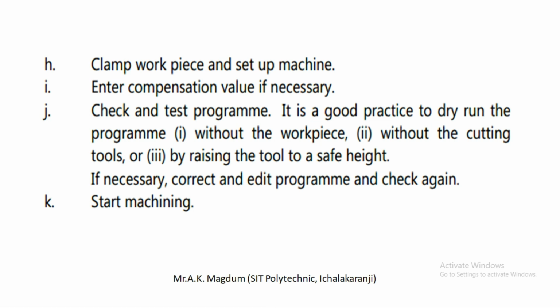Next one, enter compensation values if necessary. Tool compensations are there. We want to mention those compensation values in the program itself, because then and only then will you manufacture an accurate and precisely dimensioned job with the help of that CNC machine.